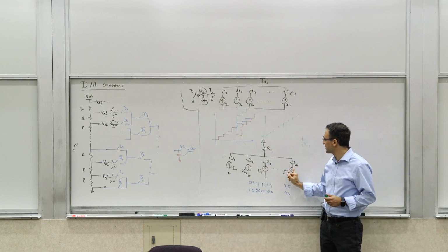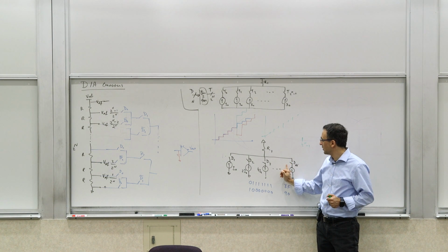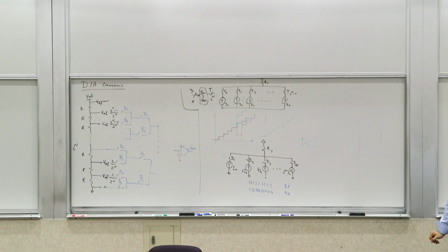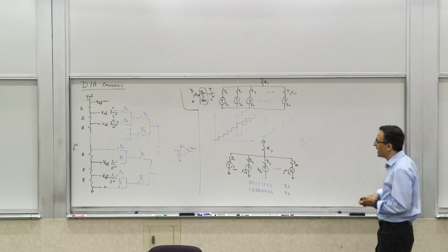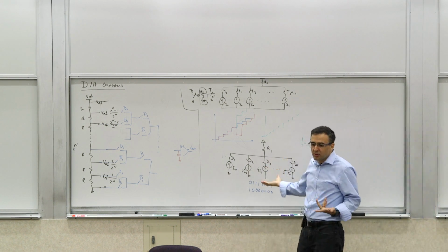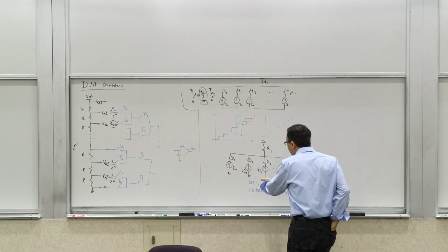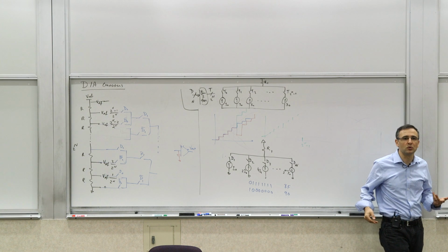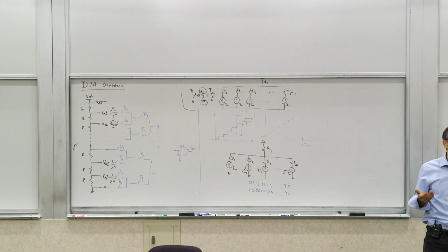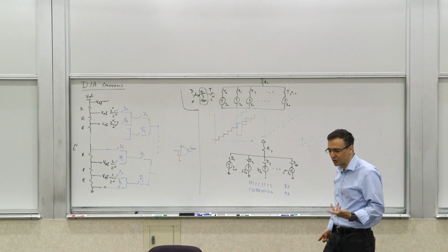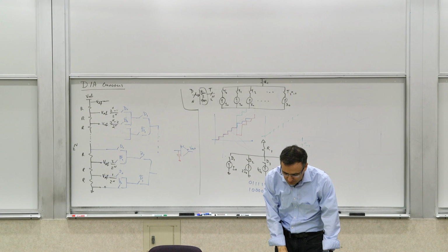Because that's when you're transitioning from the largest current source to the next one, or the second largest to all of them, and so on and so forth. So that kind of thing can happen, and that would be an issue. But in principle, you can make this. Now, usually you make these things up to 8 bits or maybe 10 bits. When you want to go to higher levels, then the levels of matching required makes this not very good and reduces the resolution, practical resolution or effective number of bits that you get out of these things.